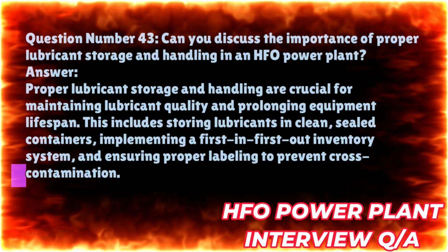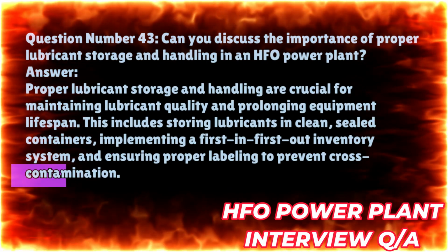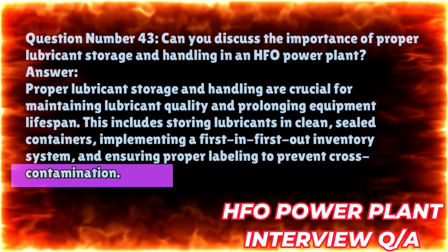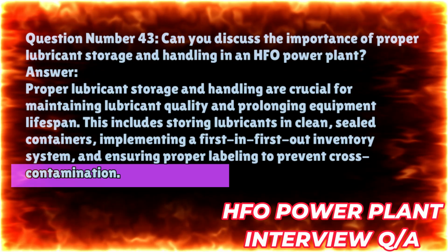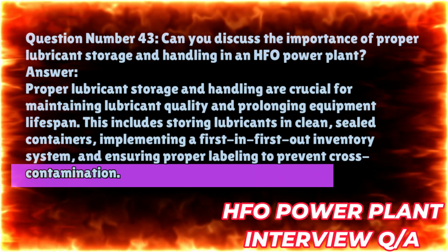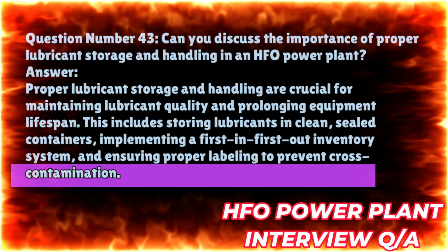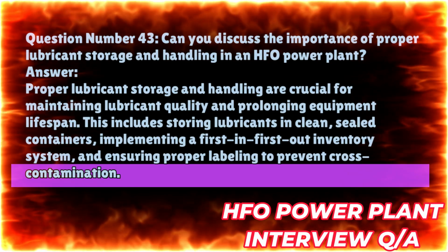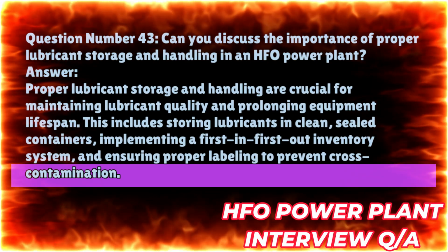Question number 43. Can you discuss the importance of proper lubricant storage and handling in an HFO power plant? Answer. Proper lubricant storage and handling are crucial for maintaining lubricant quality and prolonging equipment lifespan. This includes storing lubricants in clean, sealed containers, implementing a first-in first-out inventory system, and ensuring proper labeling to prevent cross-contamination.